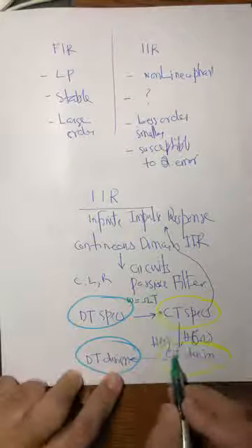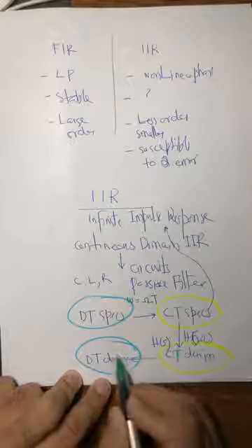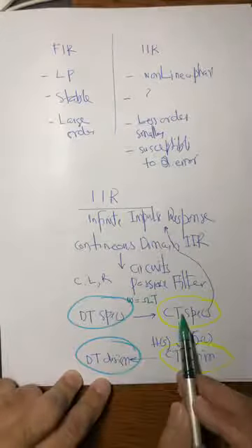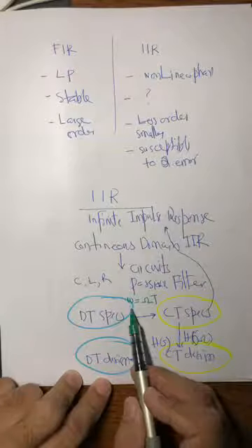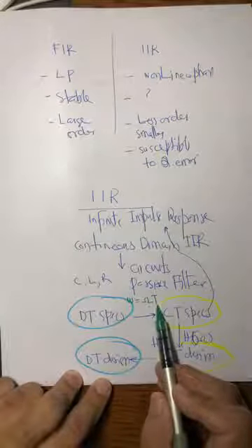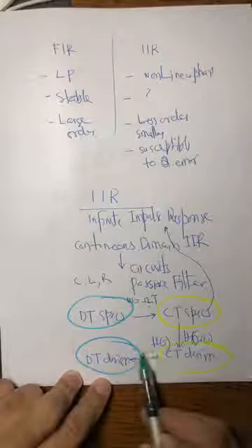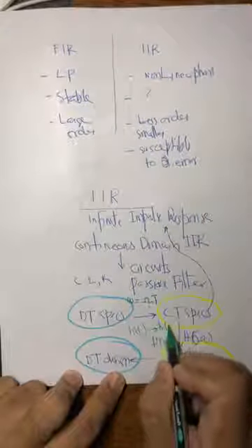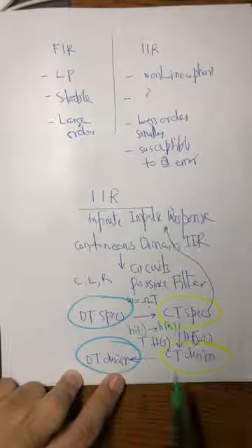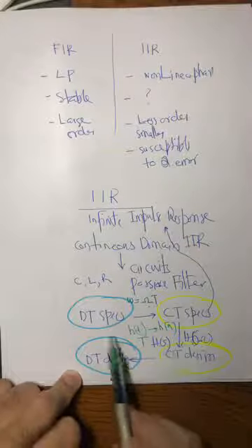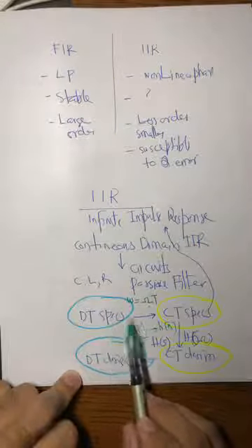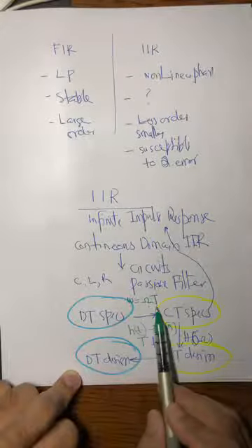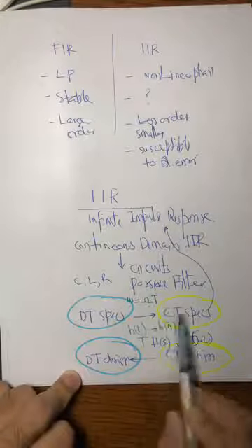Okay, and then once you come back from here, you again go back from the analog domain to the discrete domain. So what you do is, you change the specs to continuous domain specs, meaning small omega is converted into capital omega with this capital T. And once you are here, you again sample and convert h of t into h of n, assuming some T. And here the T really loses its meaning. It is like I ask you that a dollar is 5 rupees, because I know I have to convert that rupee back to dollar. So whatever rate or whatever value of T you take is okay, because it is a two-way transaction.